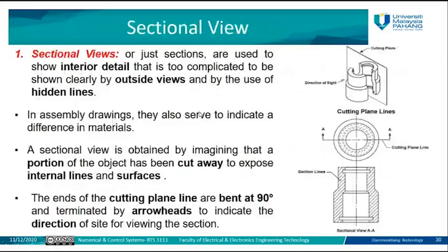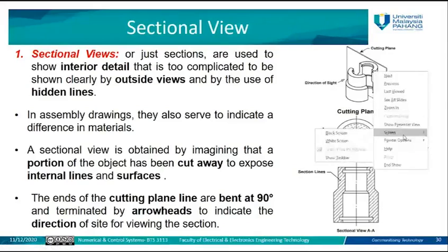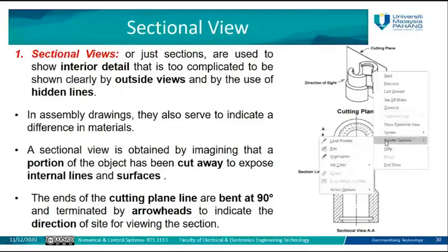For the sectional view, you cut the product or object in order to see the cross-section of this object. What is inside? Is it a cylinder inside, or is it solid? When you cut it, you can extract more information about the product. For example, you put a cutting plane in the middle of the cylinder, so you have such a view here.